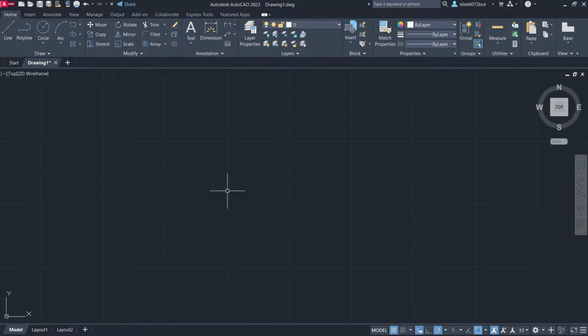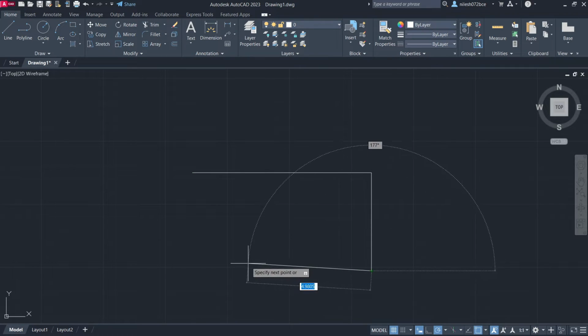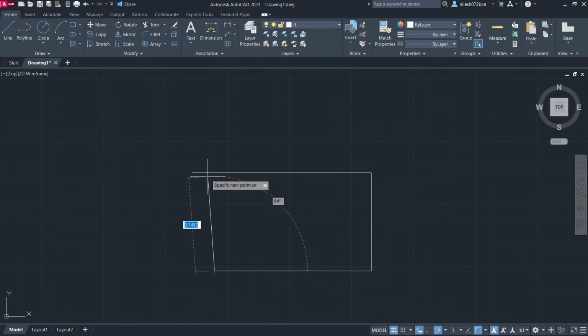If it is activated as it is now, it displays a grid pattern that covers the XY plane, and it helps us visualize distances and alignments. You can see all the lines, the verticals and horizontals. It covers all the XY plane, and it will only help us to visualize all the lines that we create here. For example, if I select the line command and draw any line, we can just visualize all the lines that we are creating here.